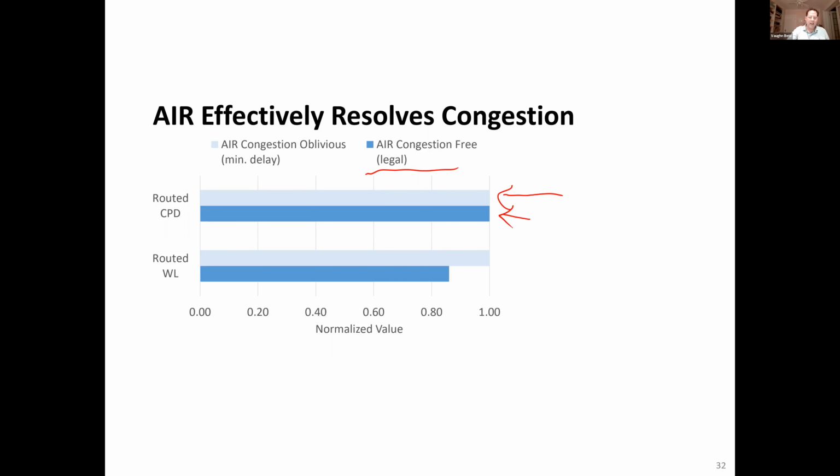The routed wire length actually goes down as we resolve congestion. And the reason is that on parts of the design that are less timing critical, the high fan-out nets will essentially reroute themselves to try to share wiring more where they can without affecting timing. So we can also see that it's resolving congestion well, despite the fact that we're trying to take a lot of shortcuts.